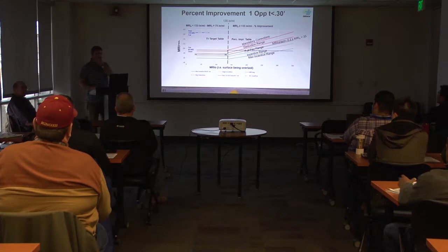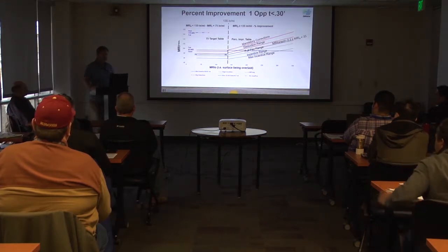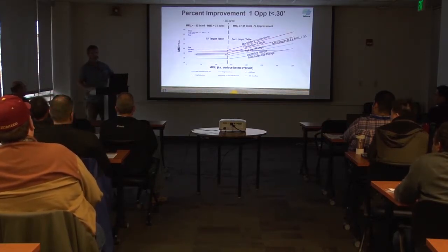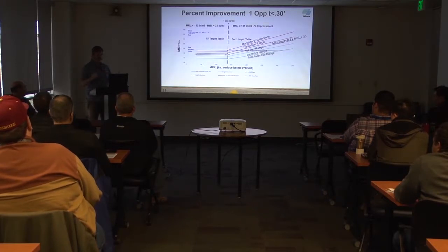What is the difference if you pave in the same shift? When you pave in a different shift, if you have a job that requires you to mill out and pave back, typically you're milling out and then you have to pave back flush. Your rollers are going to have to ride on that adjacent lane. That doesn't help you, right? If you could mill in one shift and pave in a different shift, typically you can do the adjacent lane. That will help you. So you can grind probably 2 miles before you pave.